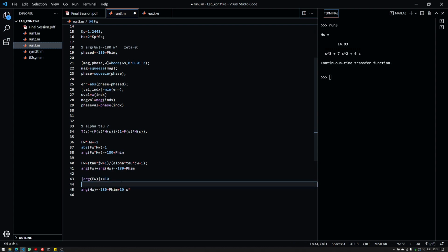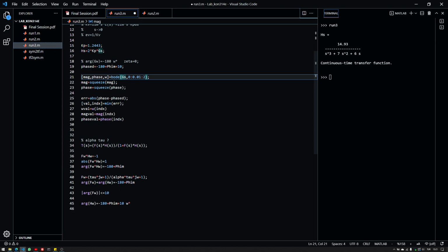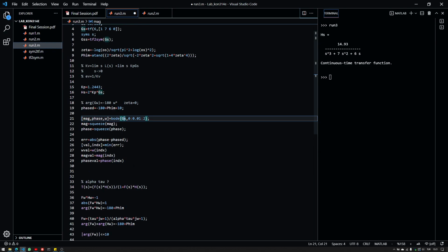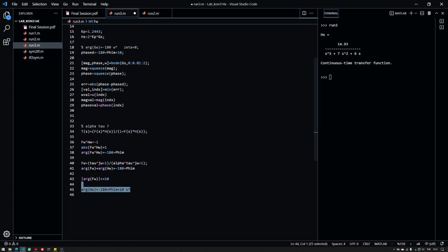So based on this assumption, I'm going to look for this angle here. So instead of having this, I will have a safety margin, which should be greater than the controller contribution in terms of angle, hopefully. By the way, if you think about it, this should be around omega star, because omega star should be the point where this should be satisfied.